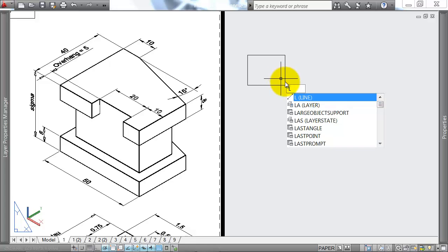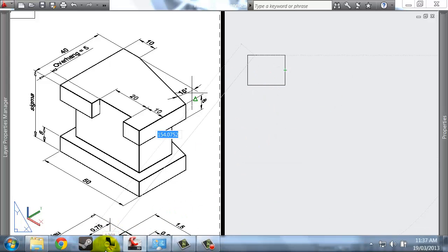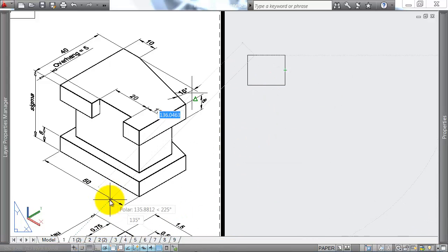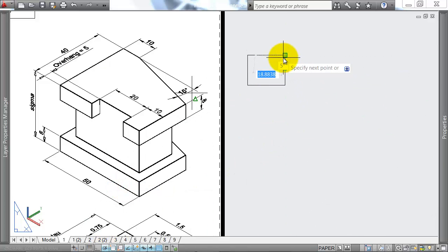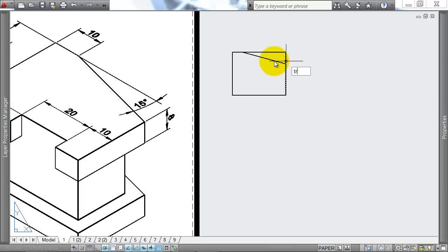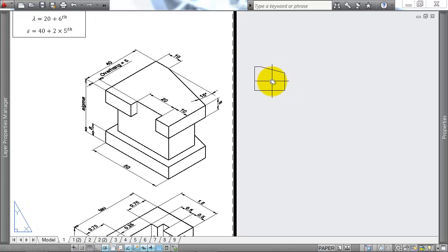Okay, what features do we have in here? If I'm looking down on the top of this shape, I see I've got this inlay of 10 units before a line at 15 degrees. So if I was doing this on paper, I'd measure across my 10 units with whatever scale factor you're using, so in my case 5. And then I'd need to set my drawing board to 15 degrees, so I can set AutoCAD to 15 degrees like so. And I can come down to here. Erase my construction lines. So this is the start of the top part of the shape.